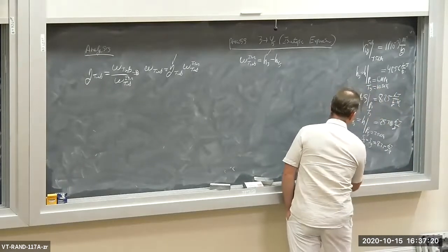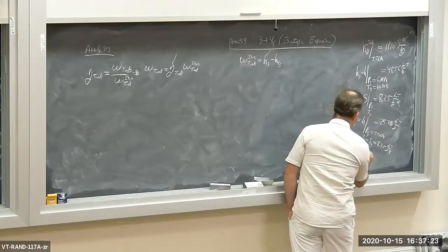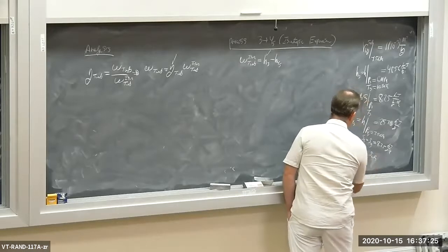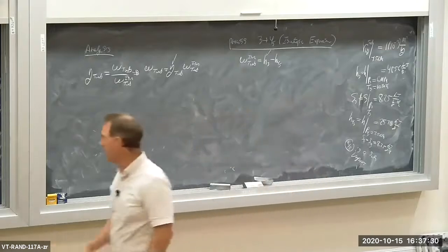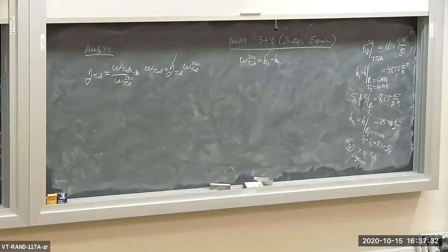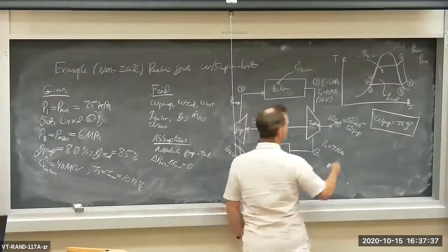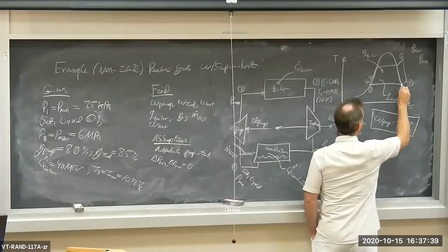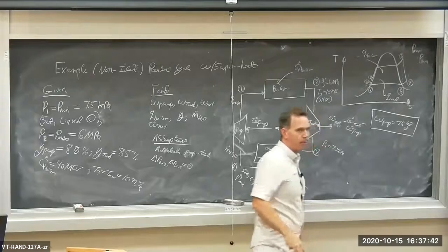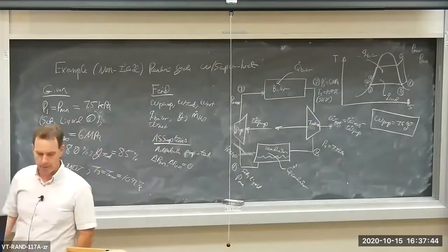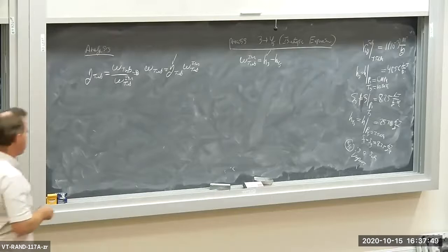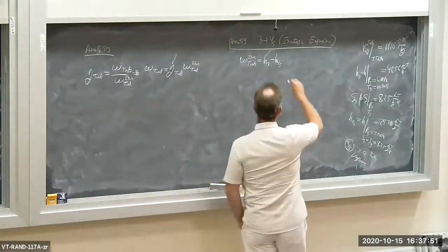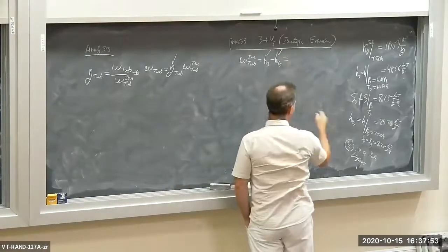So 4 sub S is a saturated vapor, okay? So hopefully my TS diagram, do I have that right? I should put the state 4 sub S there on the TS diagram. So 4 sub S turns out to be a saturated vapor. All right, so I have H4 sub S now.